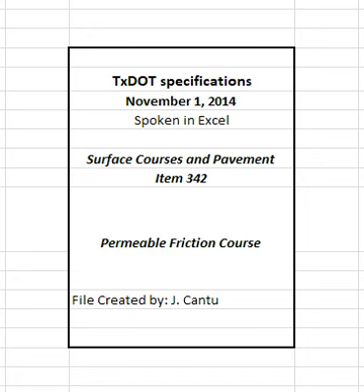Place the mixture to meet the typical section requirements and produce a smooth, finished surface with a uniform appearance and texture. Offset longitudinal joints of successive courses of hot mix by at least 6 inches. Place mixture so that longitudinal joints on the surface course coincide with lane lines, or as directed. Ensure that all finished surfaces will drain properly.